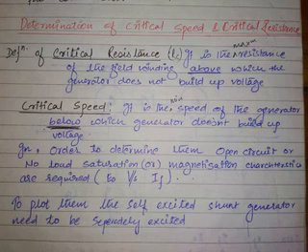You know what separate excitation is? The field circuit is independent of the armature. Across the field, there is an independent voltage source. So when you vary the voltage source from 0 to the maximum value, the current in the field winding automatically varies from 0 to maximum. You can go in finite, discrete steps. For each reading, you can measure the voltage across the armature with a voltmeter and plot the OCC. You cannot plot the OCC for a self-excited shunt generator without making it separately excited. Remember that.